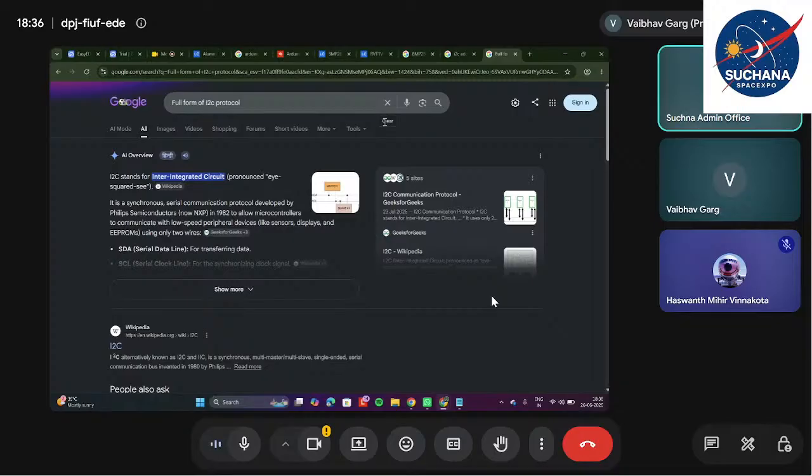If the SDO pin is connected to high, the I2C address will be 0x77. So for one BMP module, you can connect the SDO pin to low, so it will take the I2C address 0x76. For another module, you can connect the SDO pin to high, so it will take the address 0x77. These 0x76 and 0x77 are reserved for BMP280 modules only.